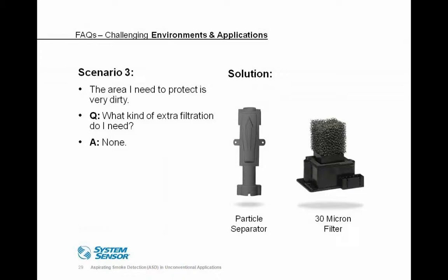Now, we monitor the airflow. I did see a question from a gentleman asking if it indicates a single hole detection. No, it's a percentage of change. If there was a 20% change to the airflow, that's when we will indicate trouble on the piping network, and also on the filter, so it is measured across the filter. It isn't a time, like historically. The detector will tell you when it needs to be replaced.